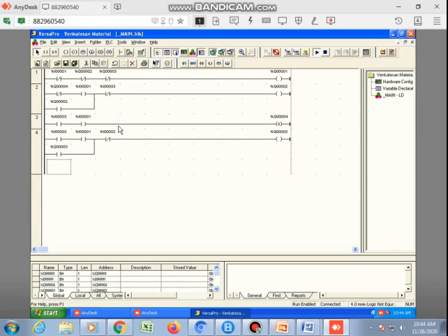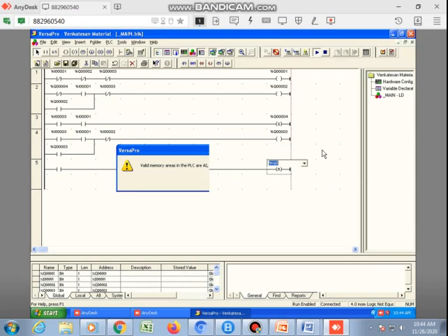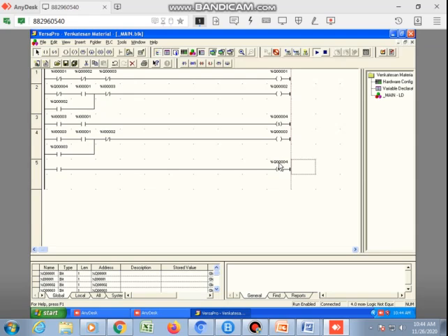So when I reach my end position, that is percentage I2, I should reset my what? Electromagnetic switch. What is your electromagnetic switch? That is percentage Q4. I will reset percentage Q4, which will reset with respect to what? I2. So that is percentage I2.